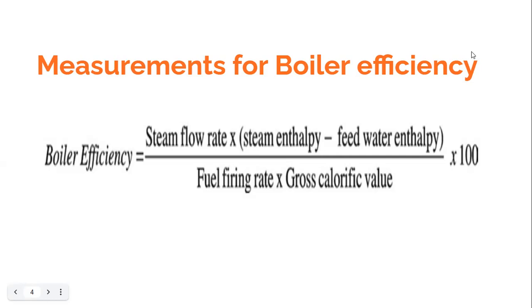So when you compare the boiler efficiency, we need to compare the two values. One, the boiler efficiency estimated on the GCV basis, and the boiler efficiency on the GCV basis given in the boiler supplier's sheet. Or the boiler efficiency we need to estimate on the NCV basis and compare it with the boiler efficiency given by the boiler manufacturer on the NCV basis.